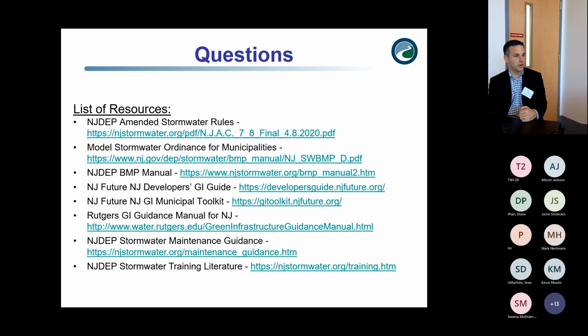But I would say that you do want to be planning for, 50 years down the road, what's that groundwater level going to be like? It's pretty easy to calculate based on the projections of sea level rise, especially in those coastal areas. As that sea level rises, it's going to raise the groundwater by almost the same amount. So I think that's something that definitely needs to be considered, especially when we're designing for resiliency in coastal areas.